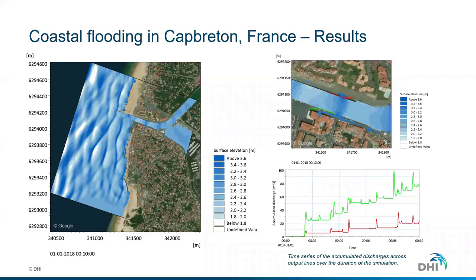Here you can actually represent the landmass as bathymetric features and just let the model handle the overtopping and the rundown of the waves. So you don't have to draw these lines along the beaches and the channels. You can model those as bathymetric changes within the model.